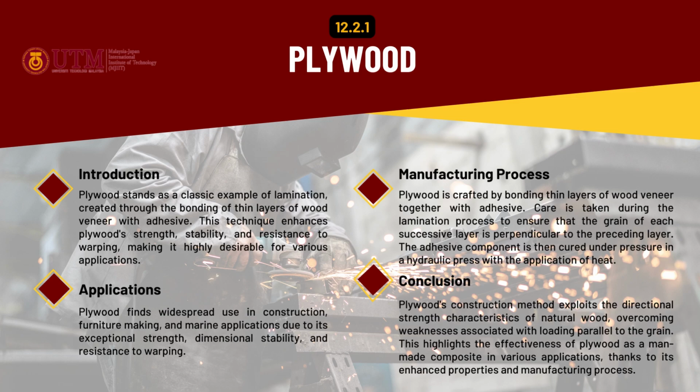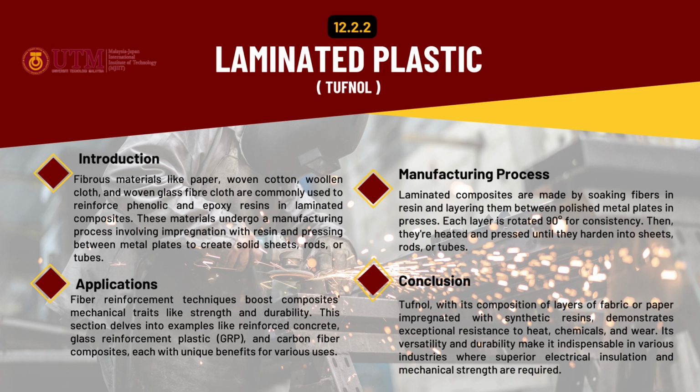I have mentioned laminated plastic or Tufnol. Fibrous materials like paper, woven cotton, woolen cloth, and woven glass fiber cloth are commonly used to reinforce phenolic and epoxy resin in laminated composites. Then these materials undergo a manufacturing process involving impregnation with a resin, pressing between metal plates to create solid sheets, rods, or tubes.